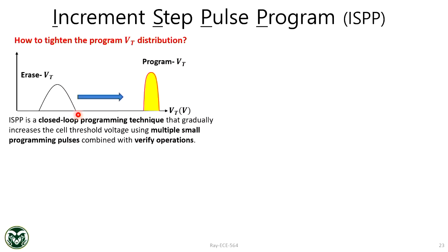We are making millions of bits in one array, so that distribution is reflected here. The process variation is fundamental variation due to the fabrication process. You cannot make all the cells precisely, say, 6 nanometer thick tunnel oxide. Some tunnel oxide will be 7 nanometer thick, and that will change the threshold voltage. Some can be 5 nanometer thick. So that is the initial variation. You cannot control that, but you can control this.